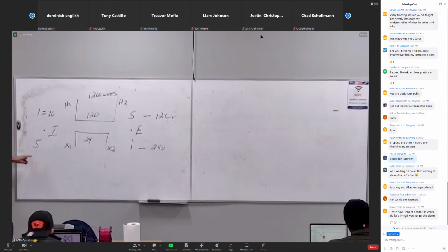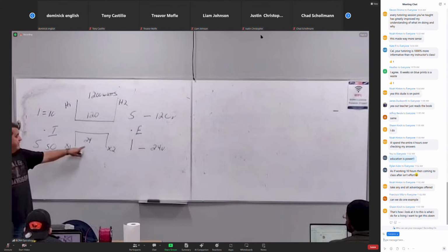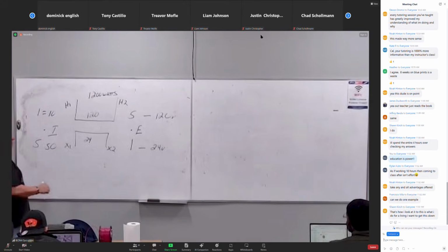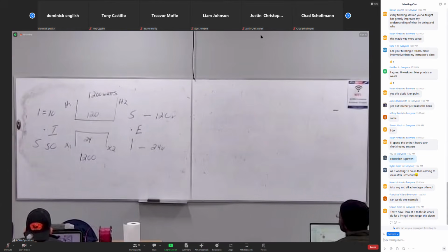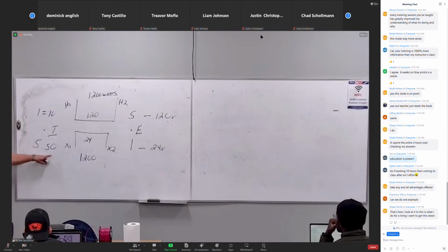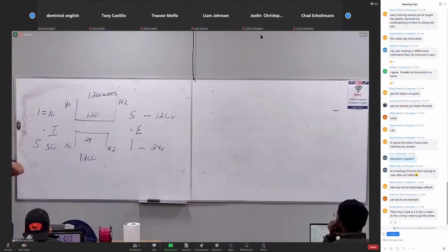All right. This means it's what? I don't even have to do a calculation. This is 1, that means this would be what? Yeah, 5 times greater. 50. If I don't trust it, I can check it. 50 times 24 probably equals what? 1200 watts, because power in equals power out. If I have 1200 watts on the primary, I have 1200 watts on the secondary. But notice what happened. When I lowered the voltage, the current went up. When I raised the voltage, the current went down. They're inversely proportional, always.